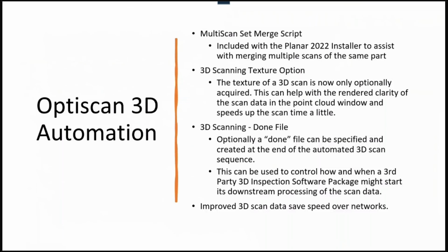Basically, you scan 3 different parts on the table, 3 different views, and as long as all those 3 CAD files or point clouds are in the same folder, you run the script, and it'll individually grab each one, fit it to CAD, grab each file, fit it to CAD, and when you're done, then you fit all three of those individually to each other, got the full CAD file done.